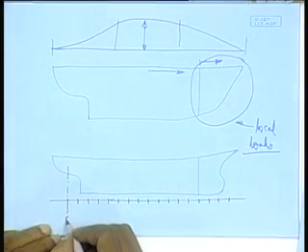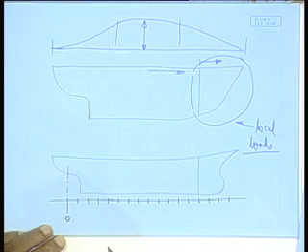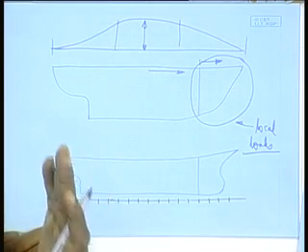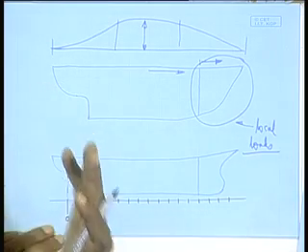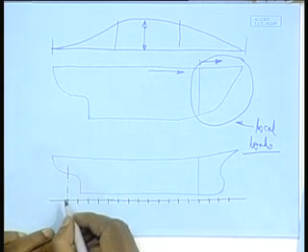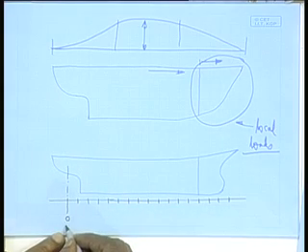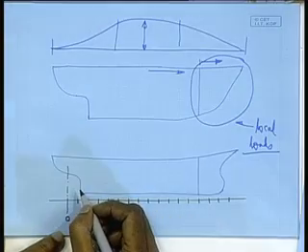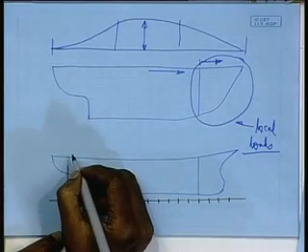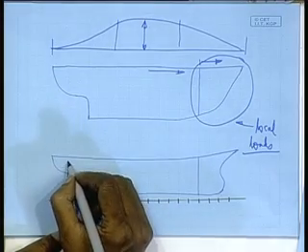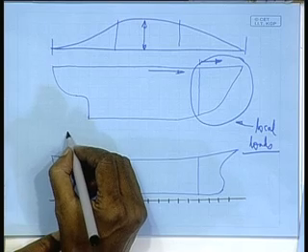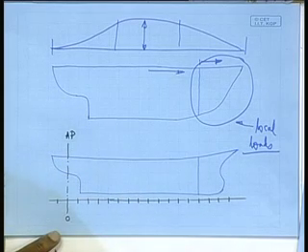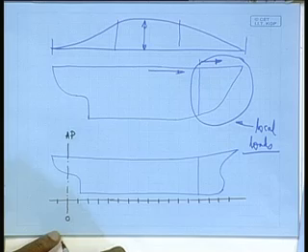Now, it should start from a 0th frame. That is fixed, wherever you want to fix it. Generally, by convention, it is fixed at this point, which coincides with the, what is this line? After perpendicular. Generally it is done that way, so let me write here, after perpendicular. So, this frame here becomes what? Minus 1, simple.